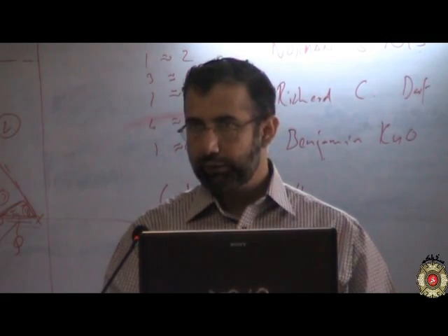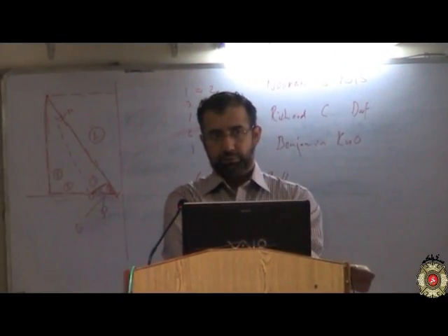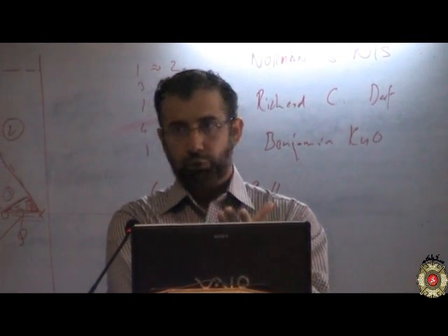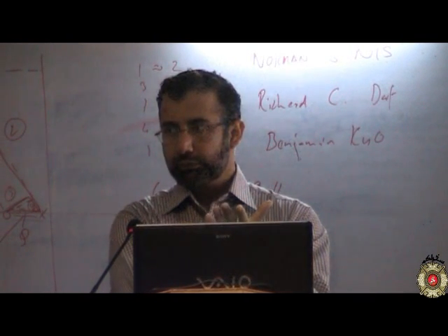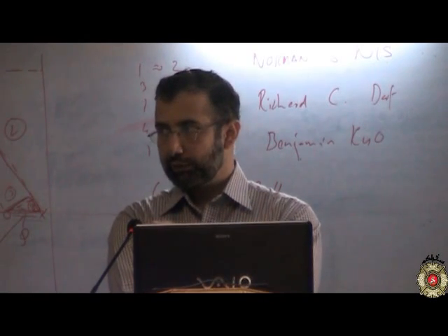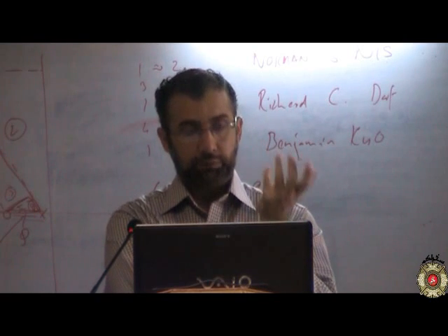Whenever we are resolving the forces, we do not say that, oh, the components of the pressure are, no, absolutely wrong. The pressure force has components. And how do you get a force from a pressure? Force per unit area, right? F is P times the area. That gives you the force due to that pressure. So that is kind of a nitty-gritty stuff, but a conceptual thing.